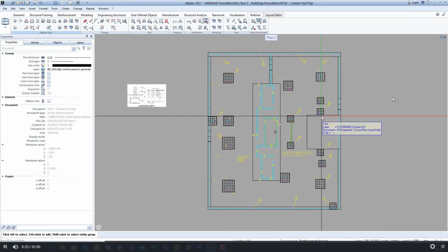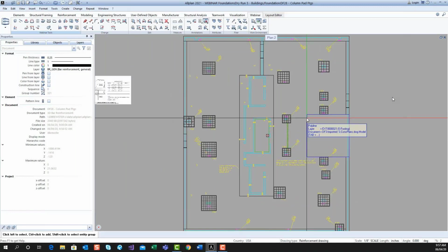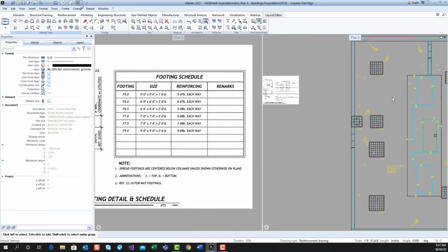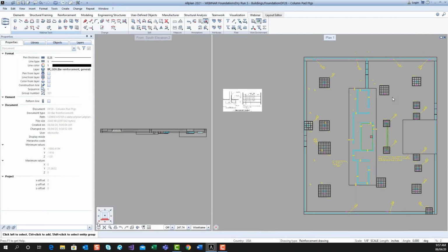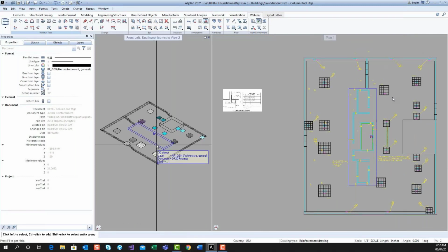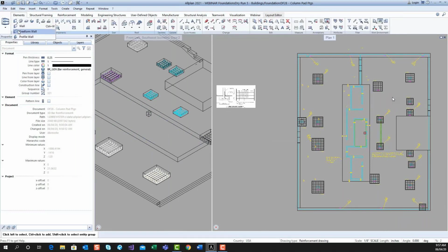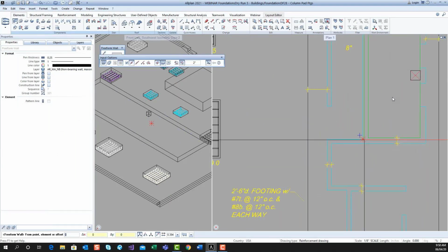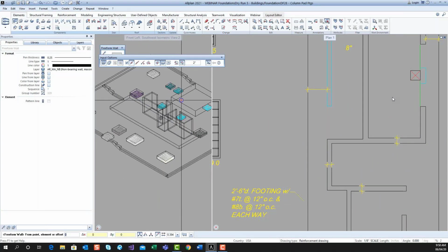So for the most part, without me blabbering on, we're 8 minutes in. We've got most of our concrete in. There are some walls in here. There are some columns in here as well. I'm going to show you a couple of techniques for very quickly getting the walls and columns. I've already done the walls ahead of time, so I'm not going to dwell on it much. But just by clicking an internal point inside this wall, you're going to see on the left-hand side a predefined height for this wall already showing up, just by selecting inside the CAD work.